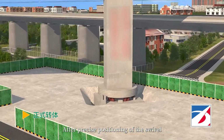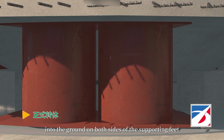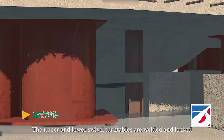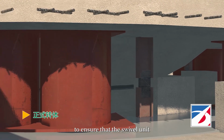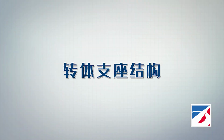After precise positioning of the swivel, steel wedges are driven into the ground on both sides of the supporting feet. The upper and lower swivel turntables are welded and locked to ensure that the swivel unit does not undergo any further displacement. 7. Swivel bearing structure.